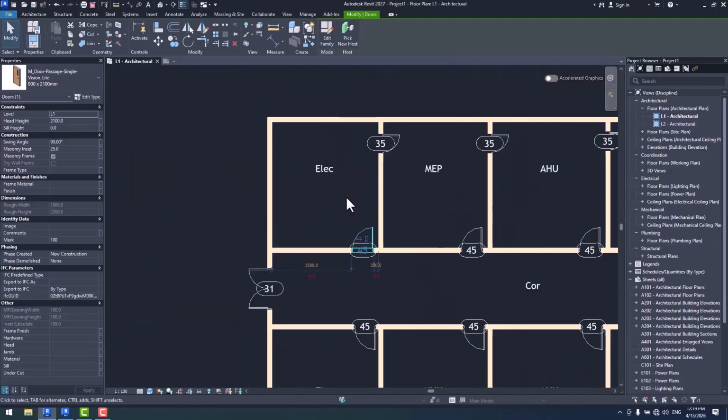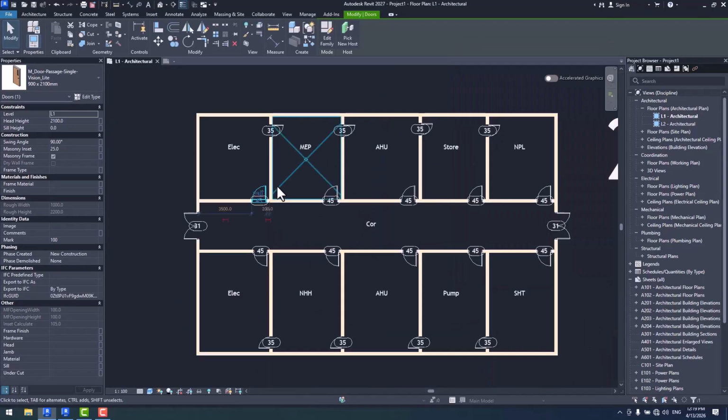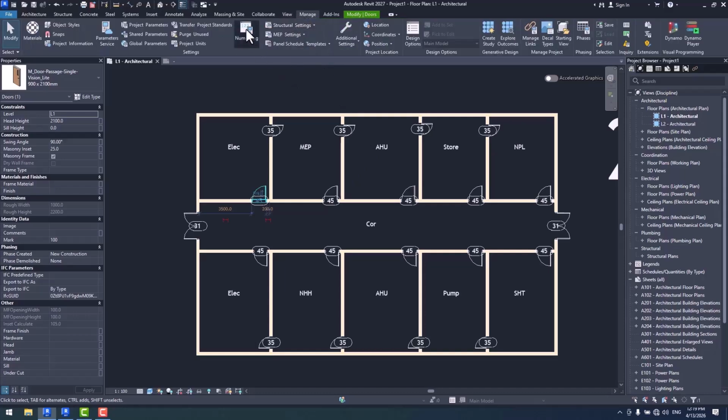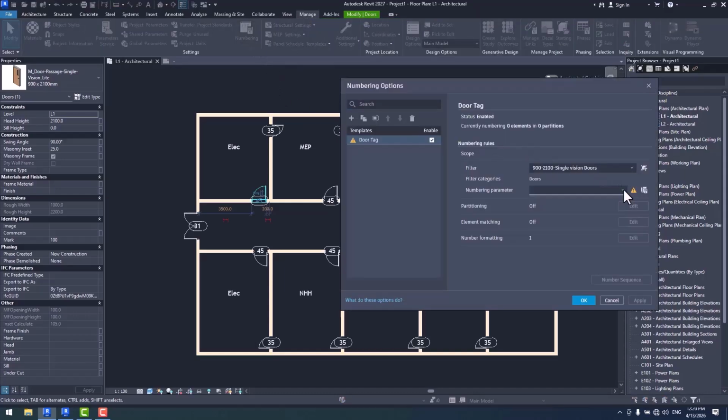Well, because obviously, applying a modification within the type properties tab would affect the entire type within the entire project. So that is not really logical when you think about it. So what we can get from this is that numbering would only work with the parameters that we would get within the properties tab. Well, type mark is not one of them.